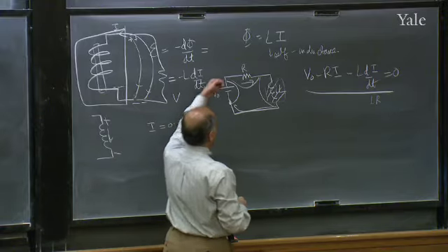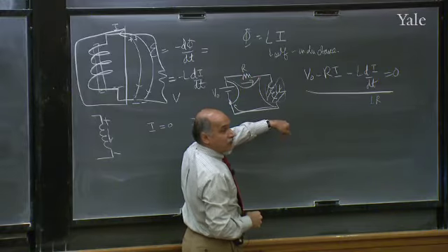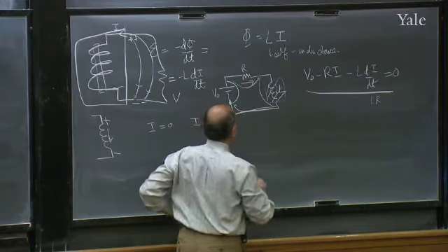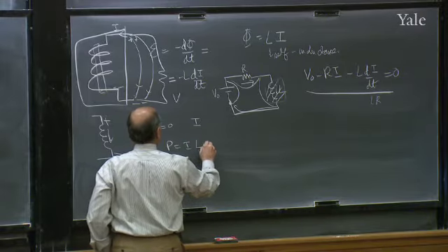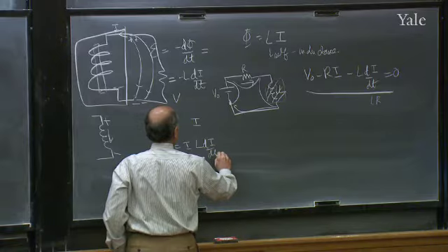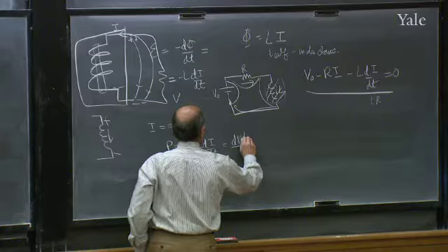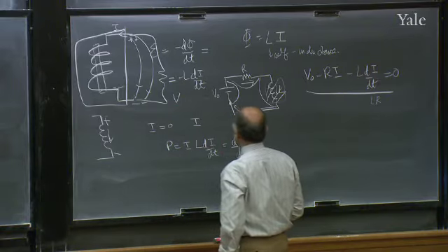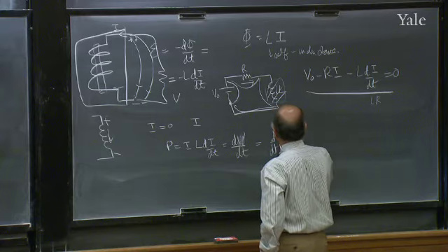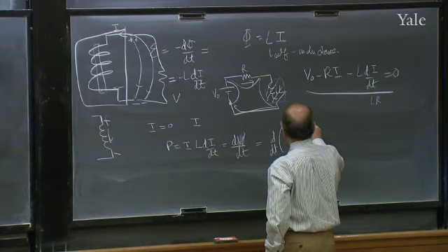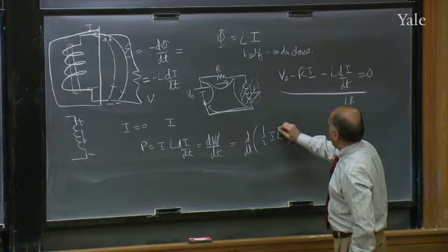Because when you start driving the current, it's opposing you with a voltage L di/dt, and you're ramming the current up in spite of that opposition, so the work you do, the power, is I times L di/dt, which, if you like, is the rate of change of energy. But I times L di/dt is d/dt of 1/2 L i squared.